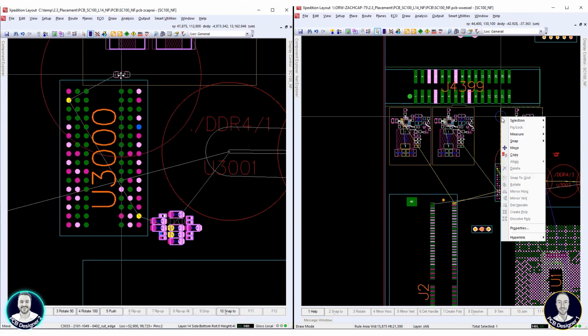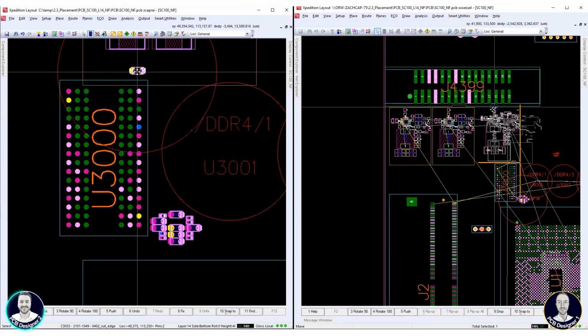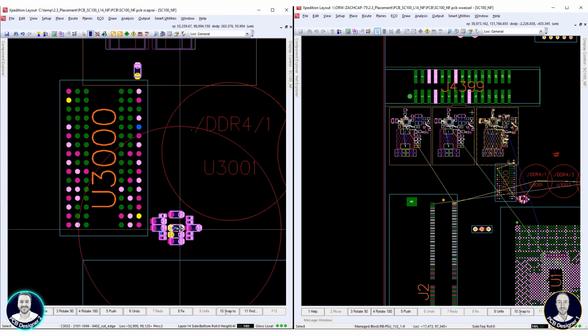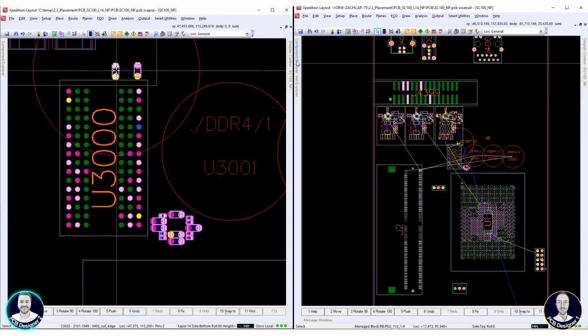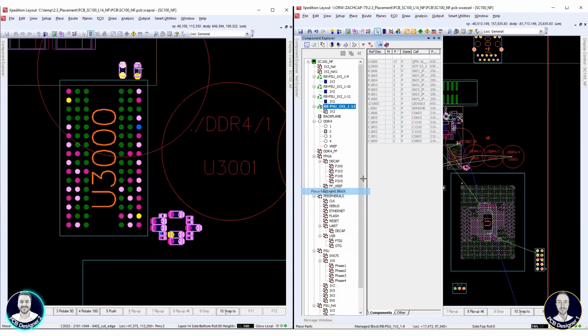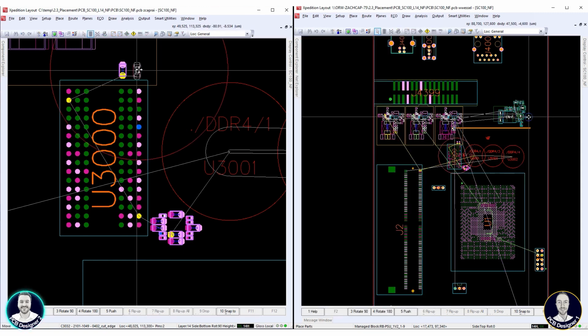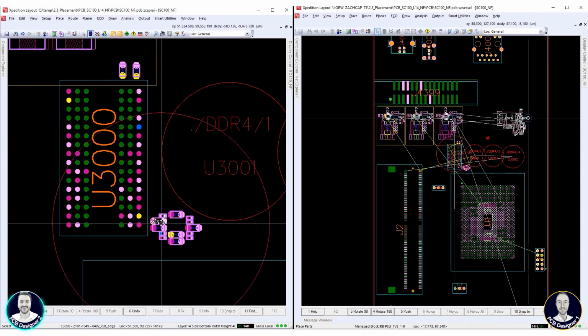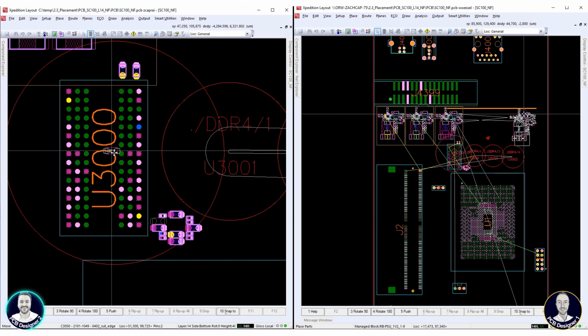Prior to arranging, I pushed that planning group to the bottom of the board, since I required that these capacitors be on the bottom layer. Now I can begin arranging a few of the decoupling capacitors in the desired topology around the first chip.